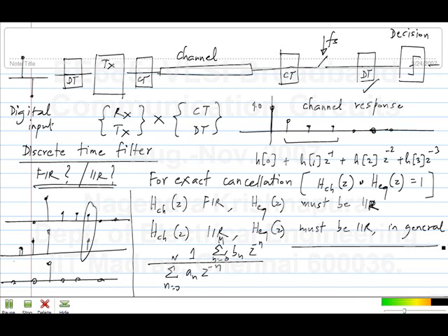So what is then the difference in implementation between IIR and FIR? Is there any reason to prefer an FIR? Okay, think of something else. What about implementing FIRs and IIRs? What are the differences? FIR, you will need a higher order to match the response of some IIR. So that is still something that is to be said for IIR. It looks like you can do more with less using an IIR filter. What else is an advantage of an FIR?